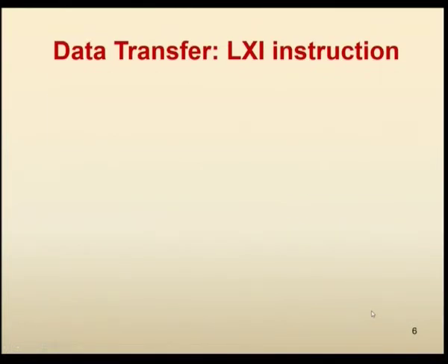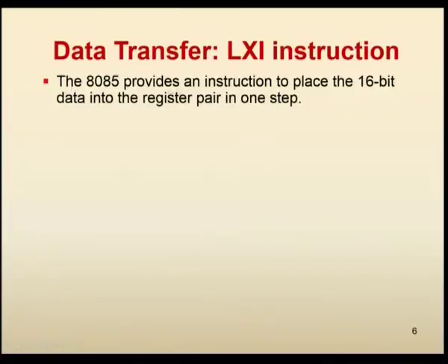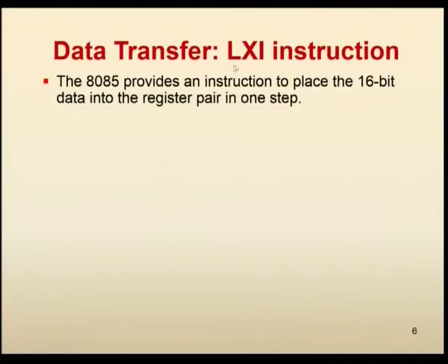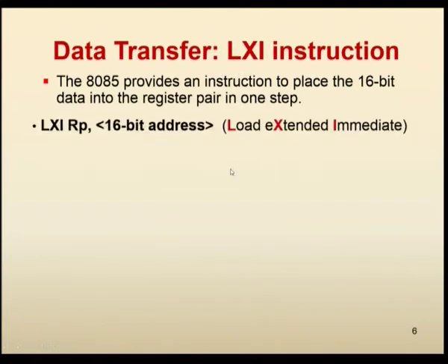Then there are other types of data transfer instructions also, let us see that. You can have 16 bit data transfer also. The 16 bit data transfer can be done again by using this instruction LXI. Although the 8085 is an 8 bit microprocessor, it provides a few instructions for handling 16 bit numbers also. One of them is the data transfer instruction for 16 bit numbers, that is the LXI instruction.